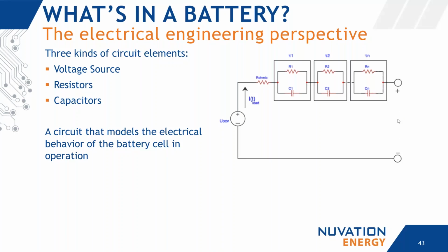And now that I'm able to put my electrical engineering hat back on, I'm already feeling much better. In this model, the resistors and the capacitors are used to represent the dynamic response of the battery to current. So basically, if your battery is completely at rest, it's been sitting there for a long period of time, these don't contribute anything. The voltage across that is 0. But as you start to use the battery, charge it and discharge it, and maybe change direction of current flow, these actually become a fairly significant part of the terminal voltage.